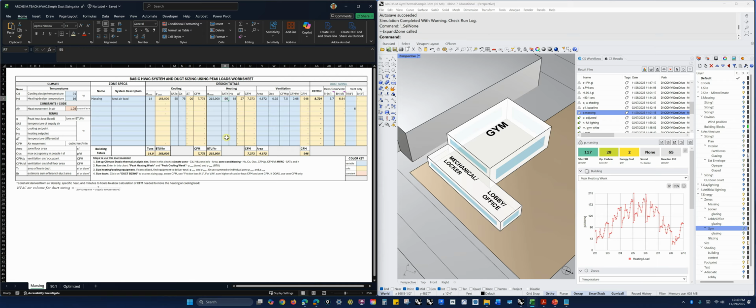So we do the same thing here. For heating, we're going to have a set point of 95 degrees. That might change based on the system you're using, but that's a good rule of thumb. That's the supply air temperature. Our heating set point is 68 degrees. That's another typical one. But again, let's say we were designing an old folks home, we might have to make that 75 or 80 or something. I don't know. So that's a variable.